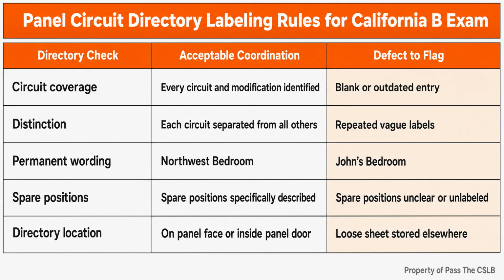The central idea I want you to remember is simple. Overcurrent protection works as part of a complete circuit, not as an isolated device. An overcurrent protective device is intended to interrupt the circuit when excessive current occurs. Circuit breakers and switches containing fuses are common examples in the equipment covered here. The protective device rating is not meaningful by itself.